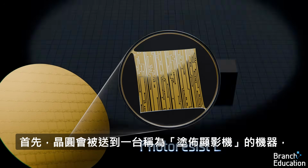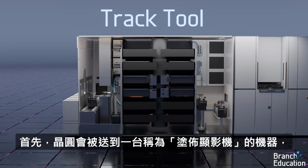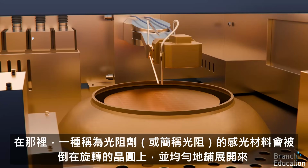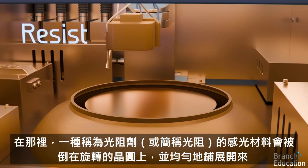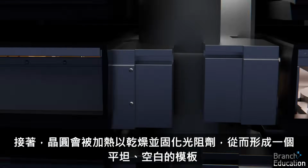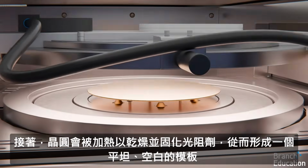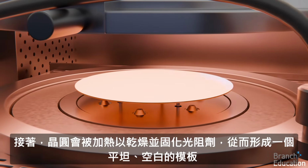layer. To begin, the wafer travels to a machine called a track tool, where a light-sensitive material called photoresist, or just resist, is poured on and evenly spread across a spinning wafer. Next, the wafer is heated in order to dry and solidify the resist, thus forming a flat blank stencil.